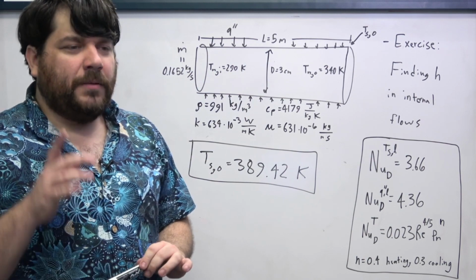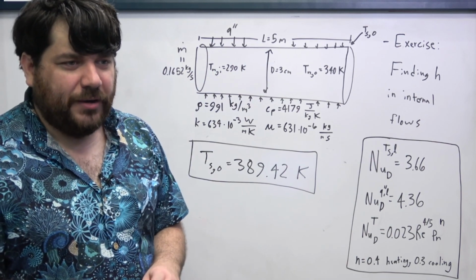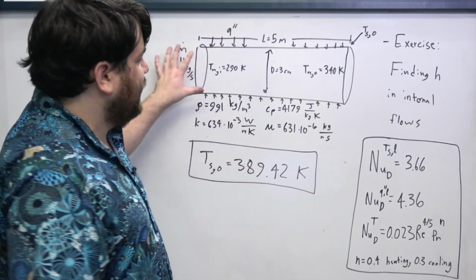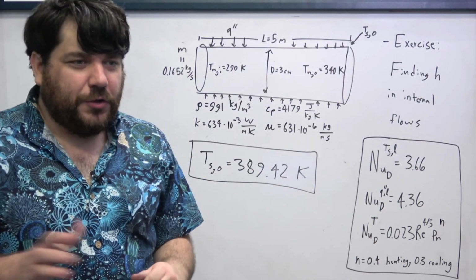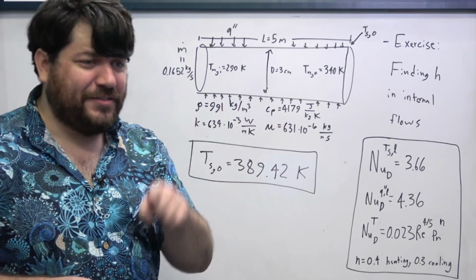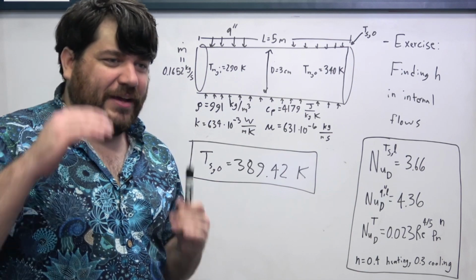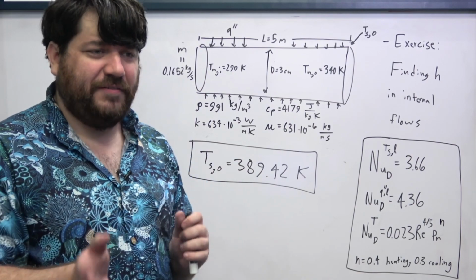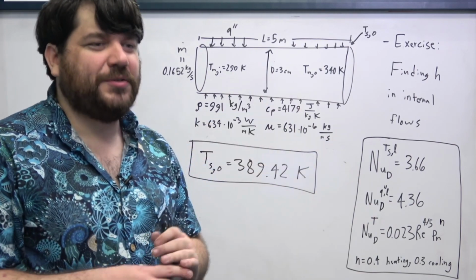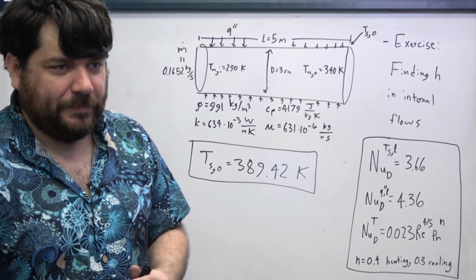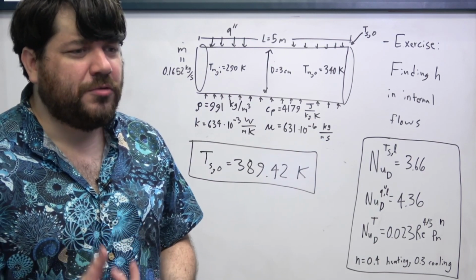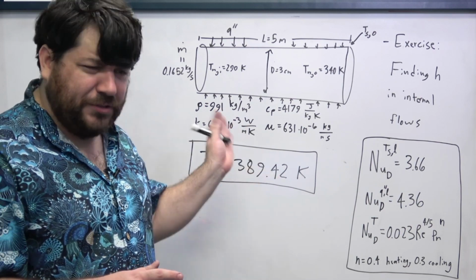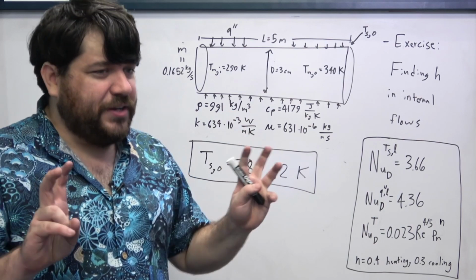But we haven't covered a specific scenario: what happens when the fact that there is a thermal energy transfer, the fact that there are varying temperatures, could affect the flow. And so you can imagine a feedback loop where maybe the temperature difference causes a flow, and then the flow affects the heat transfer, which affects the temperature difference, which affects the flow, and so on and so on. And this leads to a new class of physical system, much more complex to study, which is usually referred to with the name of free convection.